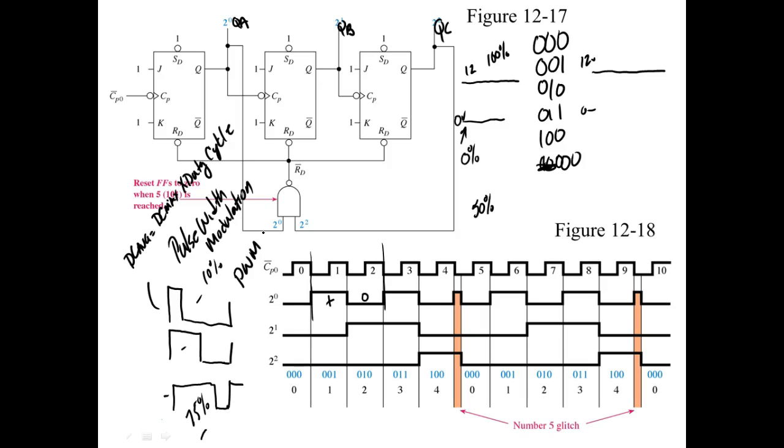Now you have to understand, solid state devices can never actually drop 0 volts. But what we can do now is control motors with a lot smaller electronic devices. And the motor doesn't care, because the motor runs off an average, right? You understand that? So I can show you this. I can control the speed of a DC motor very precisely with pulse width modulation.